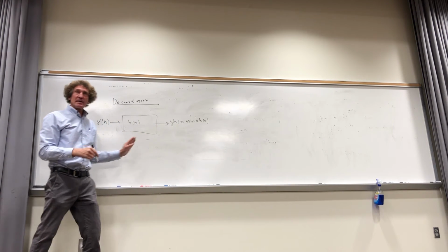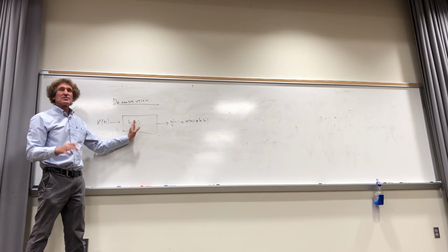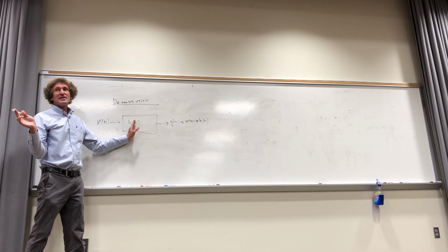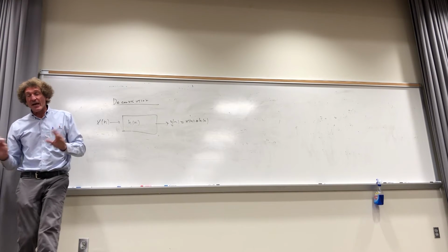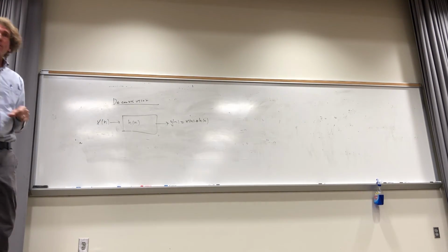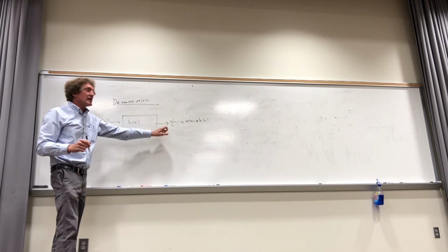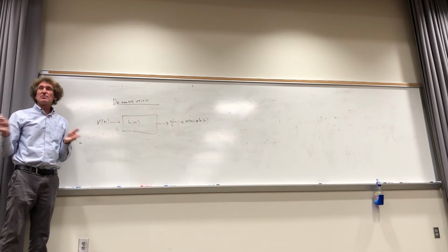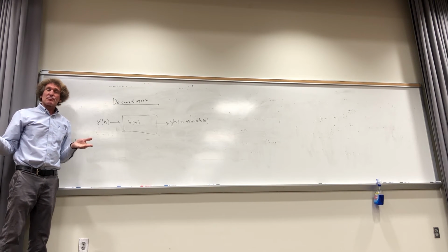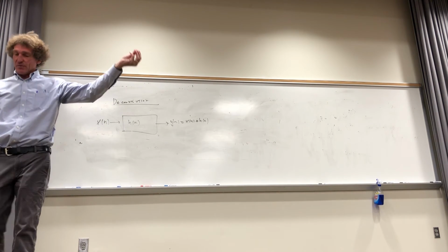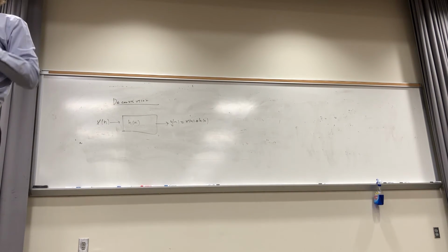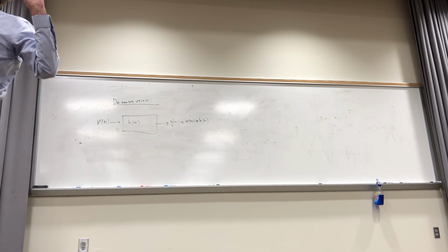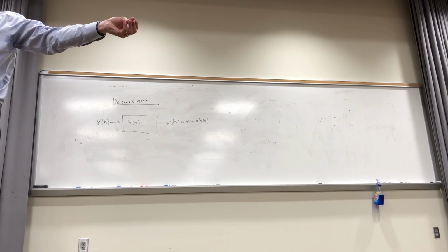Now, you may not be able to alter the design of this sensor. Try to understand this. There's a lot in this one. Dr. Dean does a lot of stuff like this, where he has sensors with a certain input-output relationship that he can't really do much about. He's got to work with it and figure out what the input was that created the output. If it's a pressure sensor and you're measuring a voltage output, the voltage isn't the pressure, but you can infer the pressure if you know the relationship between pressure and voltage.